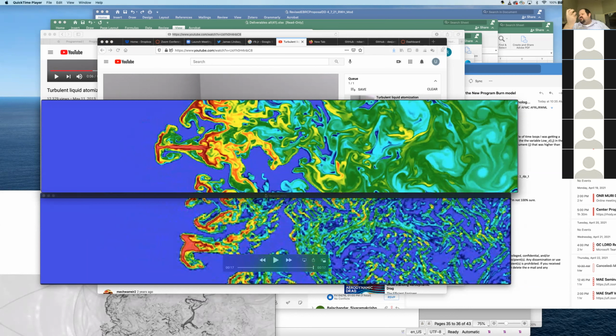Even this region here is called micromist. It's those really fine little droplets that are being stripped off. So you need a phase change model for this, where subgrid you are assuming there are a whole lot of very tiny droplets, and then you need another phase change model for when you have an actual interface. And that model does not exist, and the ability to connect those two does not exist yet.